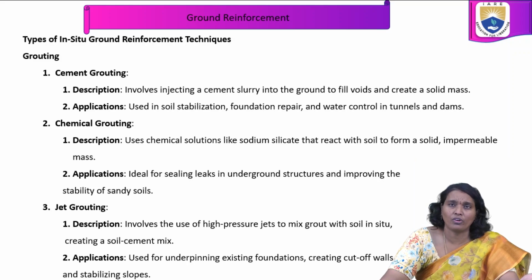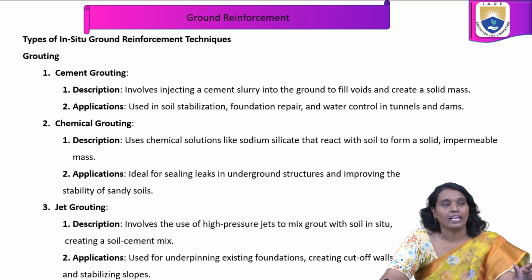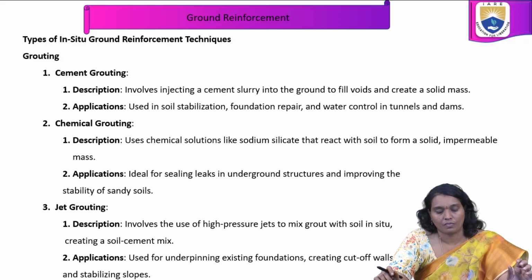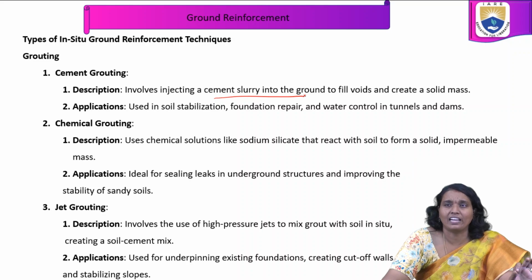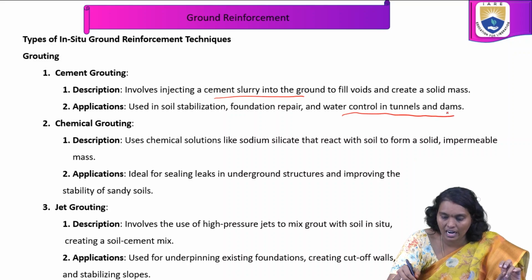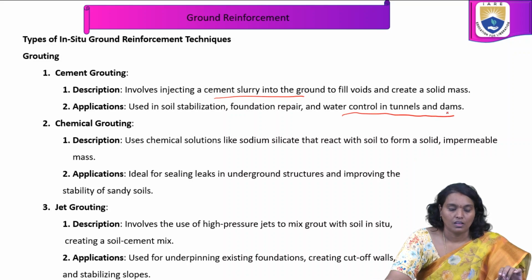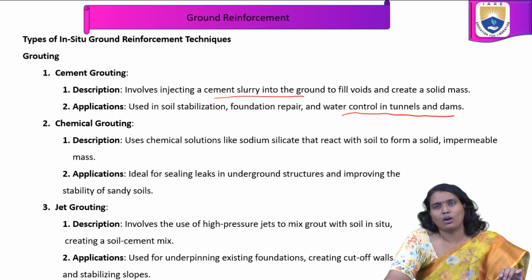We know cement grouting involves injecting a cement slurry into the ground to fill voids and creates a solid mass. Cement grouting is used in soil stabilization, foundation repair and water control in tunnels and dams. Move on to the chemical grouting.